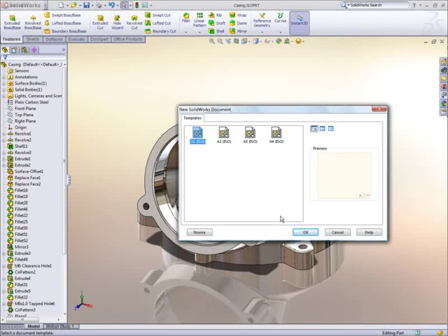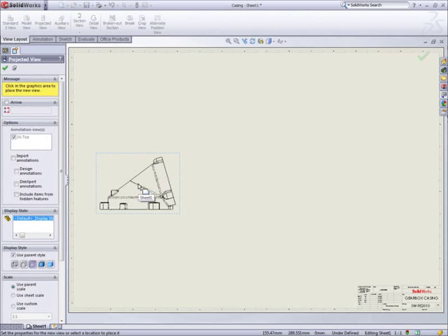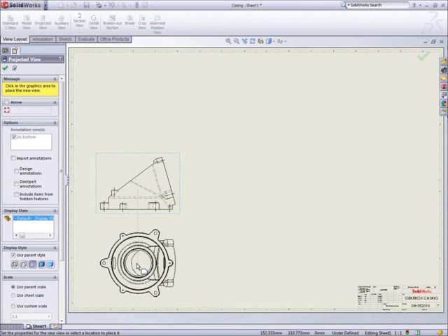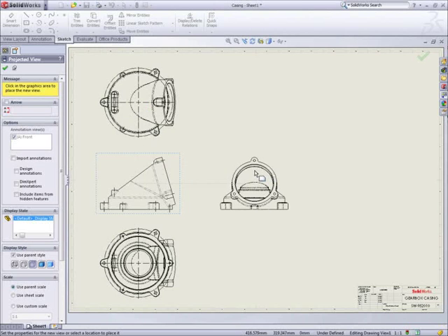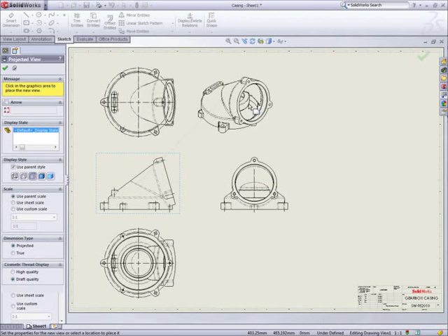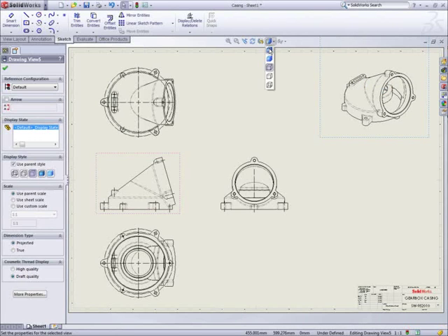The View palette shows the available views of the model, so you don't have to guess which is the front view or side view, and your working area is not hidden by a huge dialog box. Just drag a view onto the sheet and further views are projected automatically. Of course, one benefit of working with a 3D model is the Isometric View, which can also be shaded to add further clarity.